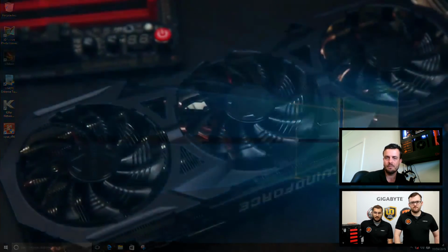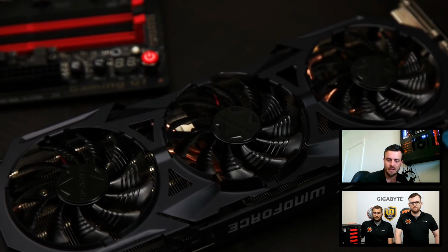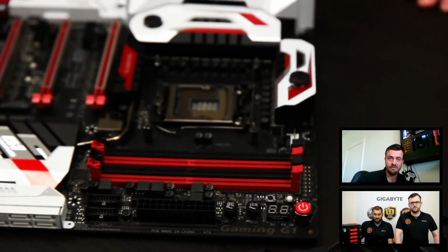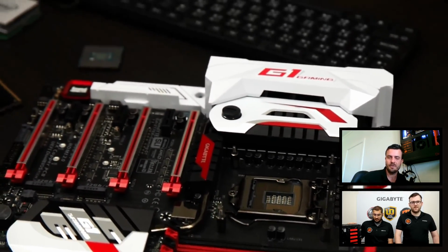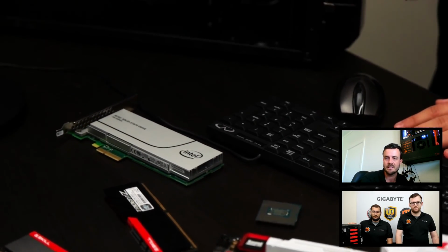It is a time-consuming process, but you will only do this really once or twice. Once you are satisfied with your results, say when 4.5 and 4.6 work, and 4.7 works and 4.8 crashes, you can drop down to 4.7 or even 4.6 just to be 100% safe. That's essentially the idea behind doing this exercise if you want to overclock. So just go slow and steady, eventually work up towards the frequency you want, do your testing, and make sure it's stable. And if you do have a crash, it's not a big deal.